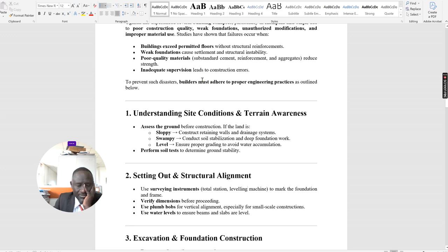So during construction, even when they're doing excavation of the site, the supervisors should attend to that, because normally they do it manually. Sometimes we indicate that foundation depth is determined and concluded from site. It means that the conclusion must be done in the presence of the engineer.